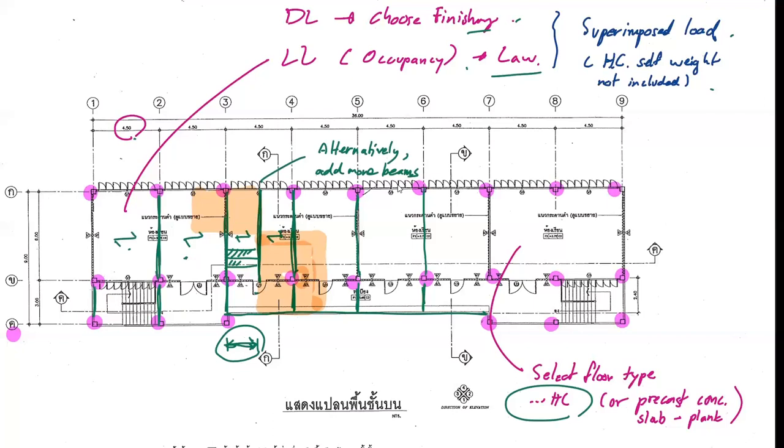So chances are, when you're dealing with a heavy structure, you reduce the span length of your floor, the size of the floor will be significantly smaller than the size of the floor with the longer length, correct? Yes. So the size of the floor here with this 2.25 meters span length should be significantly less than this. And when the floor is less, that means the weight of the entire system becomes less.